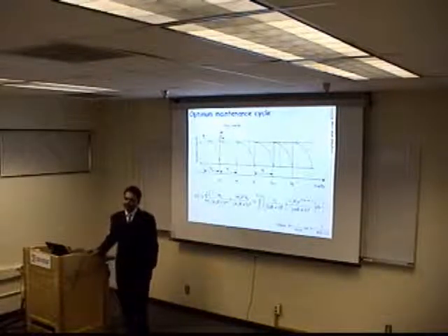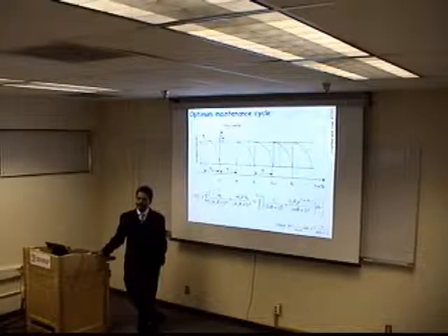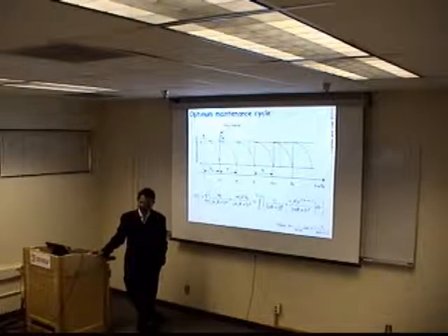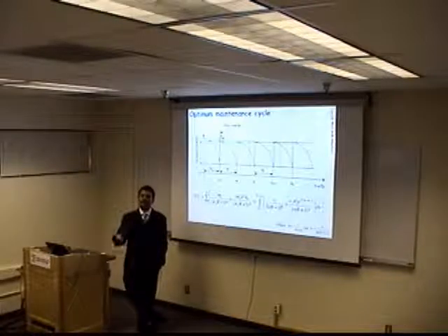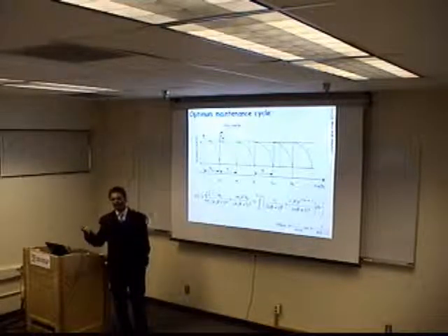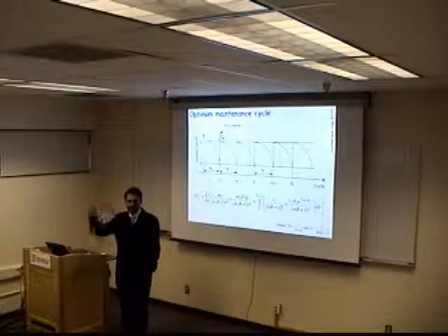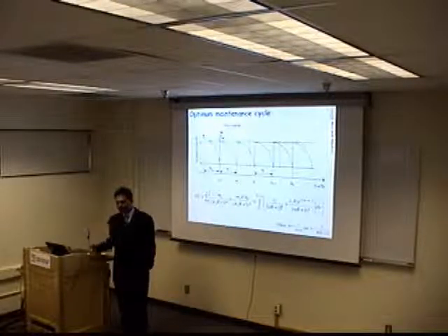And with each overlay, you are getting back to that structural capacity every time? Yes. We did some random trials and found a factor of lambda, that an addition of 100 millimeter would enhance how much of the extra life. So I multiplied with that factor.